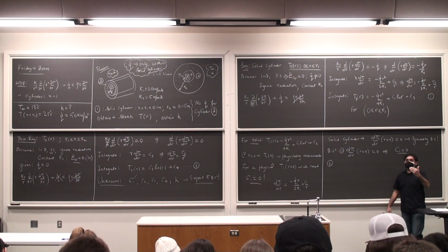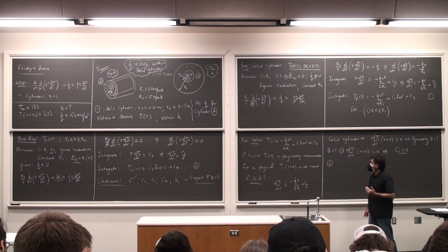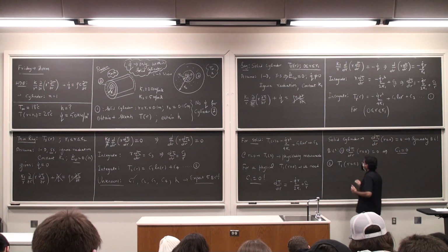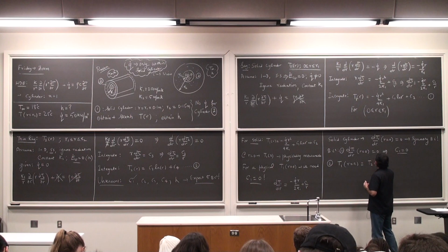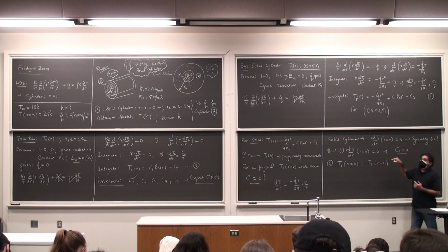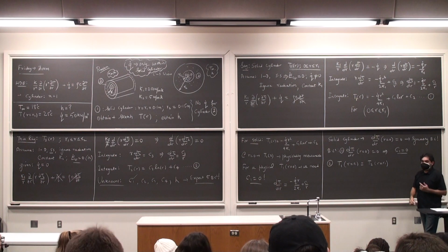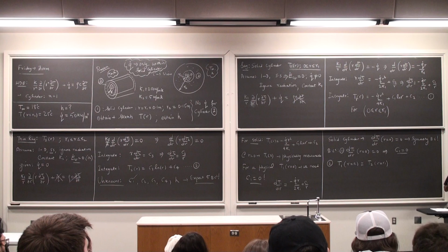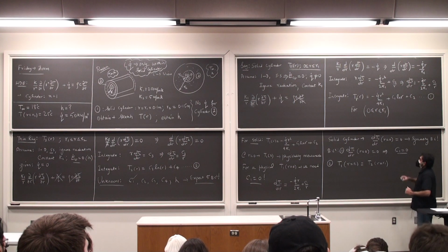So the temperature of the material with the thermal conductivity K1 at R is equal to R1, so T1 at R is equal to R1 has to be equal to T2 at R is equal to R1. The temperature value has to be continuous, the slope need not be continuous. That depends upon the material that you have and the thermal conductivity there. Okay? So this is the second boundary condition.